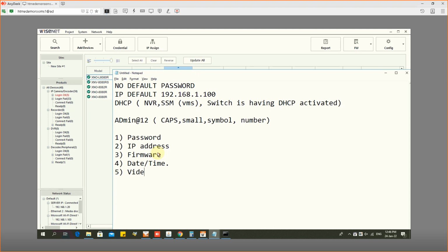Video profile. Adjusting the camera as per the project requirement. Project 1 will tell you I need recording at 1 MP 15 frames. Some other project will say record at full 5 MP, maybe 20 frames or 10 frames or 25 itself. We don't know, right? As per regulation, as per law, it will change. So how do you make sure the camera is having that setting?